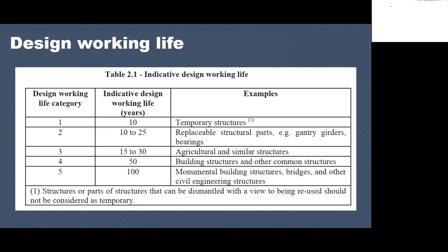If you take a temporary structure, it's 10 years, and replaceable structural parts, 10 to 25 years, agricultural or similar structures 15 to 30 years, buildings and other common structures 50 years, and monumental building structures, bridges, and other civil engineering structures 100 years.